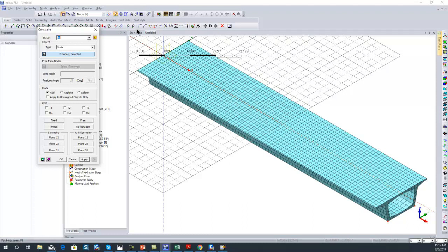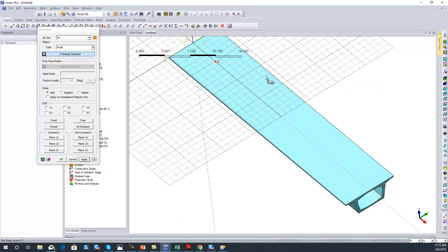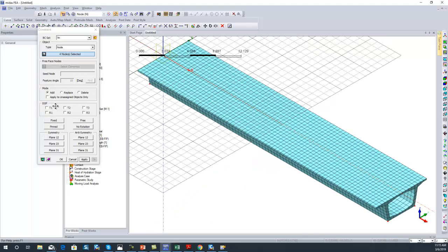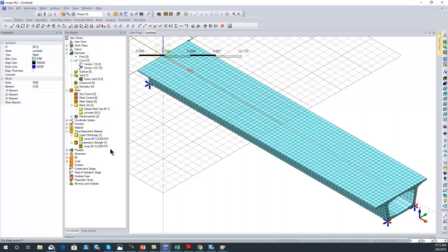And these are various options for creating the curve, surface, or the geometry. This is the option for select all. So this option can be explored. These are the options for undo, redo, likewise. So 2 nodes I have selected. I have to select these 2 nodes also. And by holding your wheel, you can rotate this, and then 4 nodes are selected. Then I am applying this fixed type of boundary condition, just to check that, and apply. So boundary conditions are applied.